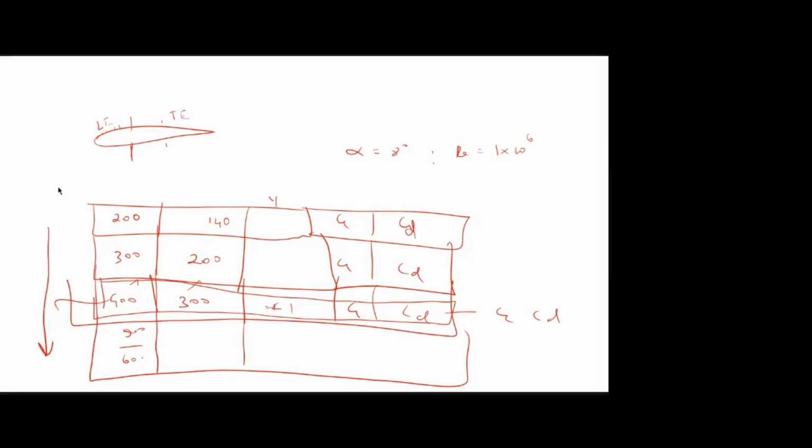Yes. Actually, there are certain errors you'll face during creating the blocking and all those things. I will explain that later when you come to the university, or else I'll try to share a video on how to rectify those things. Sometimes when you create split phases, it will create two phases on the same region, which creates overlapping phases and an overlapping mesh.